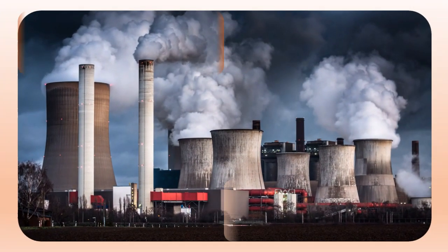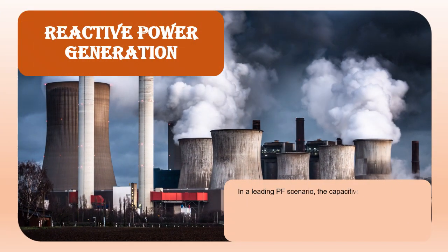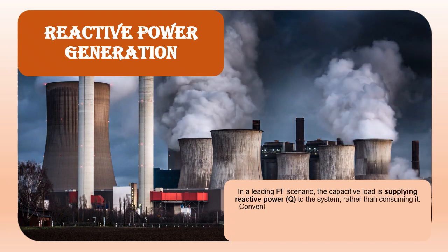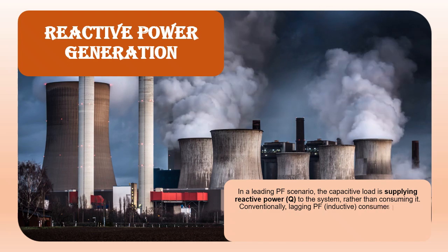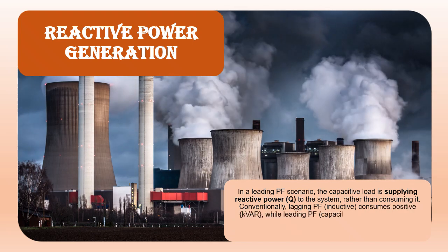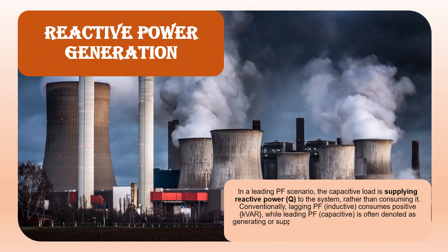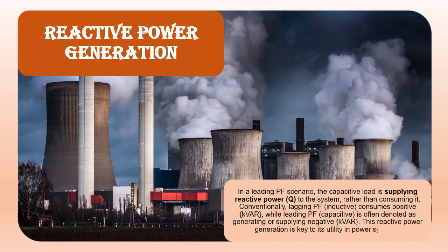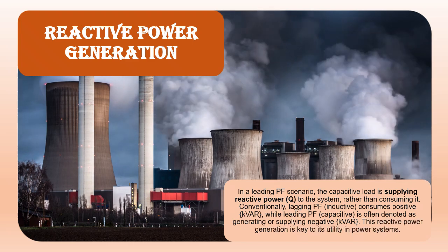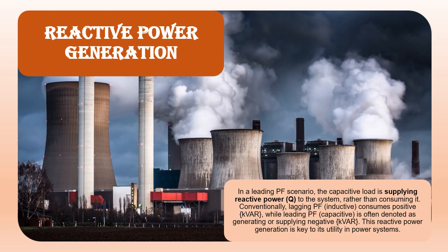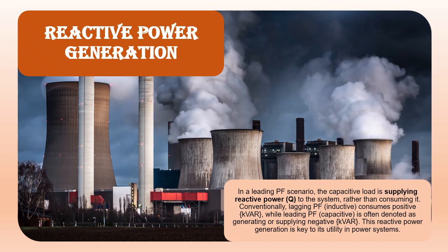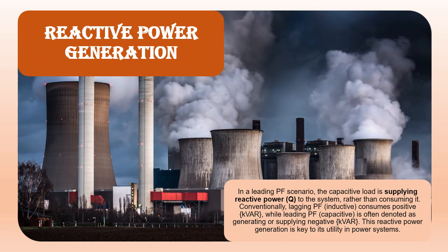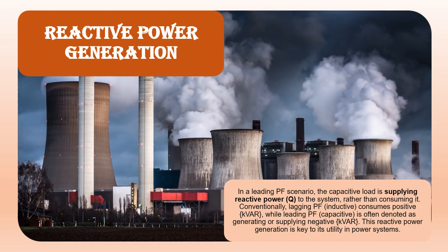Reactive power generation. In a leading PF scenario, the capacitive load is supplying reactive power, Q, to the system, rather than consuming it. Conventionally, lagging PF, inductive, consumes positive kVAR, while leading PF, capacitive, is often denoted as generating or supplying negative kVAR. This reactive power generation is key to its utility in power systems.